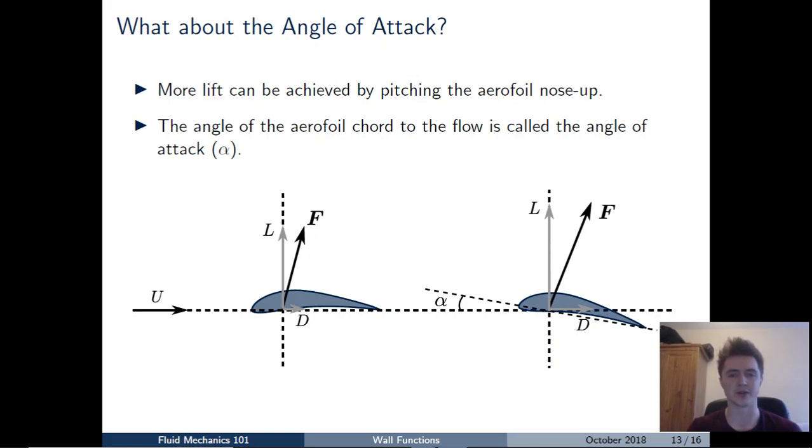And what we find is that when we pitch the aerofoil nose up, we get an increase in the lift component of that total force, and we also tend to get an increase in the drag component as well. So right away we can see that there's definitely some incentive to be pitching the nose of our aerofoil up into the flow, because we'll be increasing the lift acting on that aerofoil section, which is better for our plane.